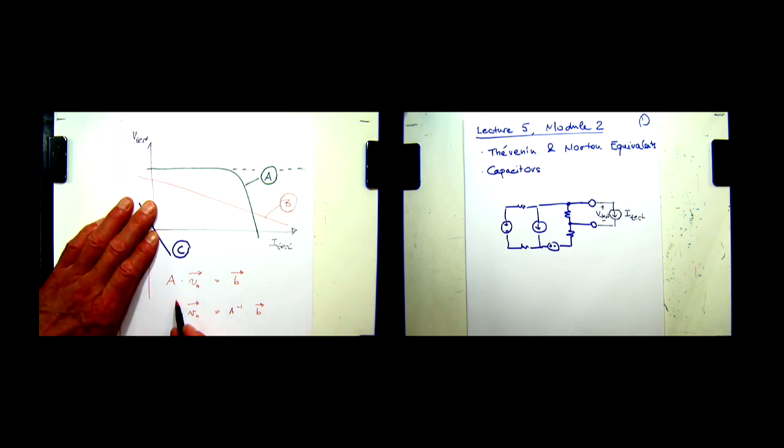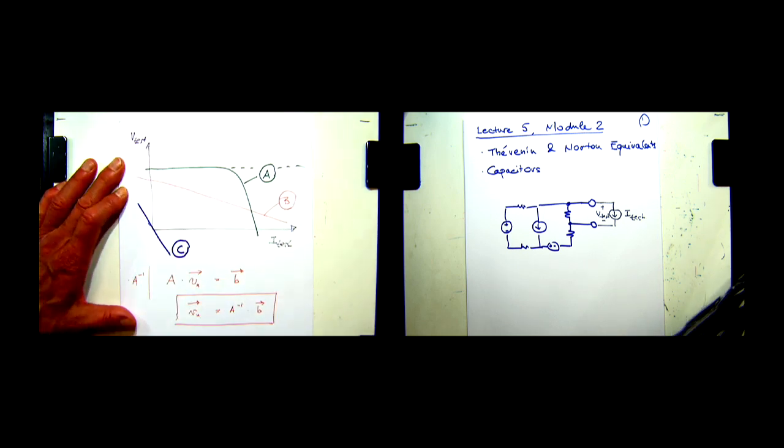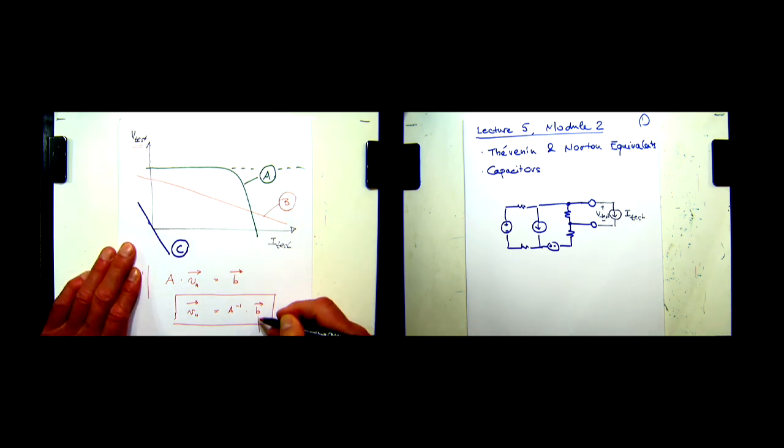Okay? So basically what this equation tells us is that all these voltages that we measure, including V-test here, are going to be simply linear combinations, appropriately weighted, of the values of our sources. Again, the voltage and current sources in that B vector. And we multiply their contributions with different values that depend on the resistors and other possible elements that we have on our circuit, the topology and so on, right? A voltage divider would be a simple case.